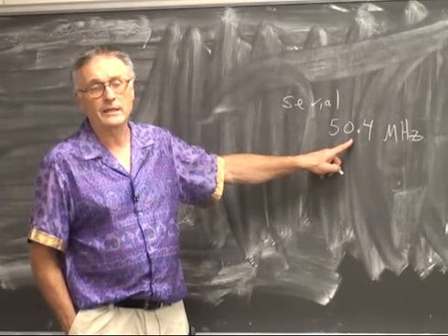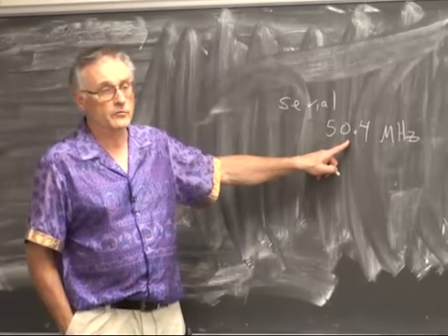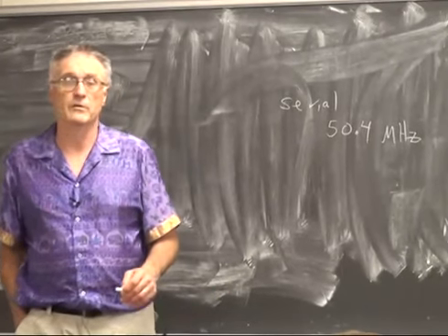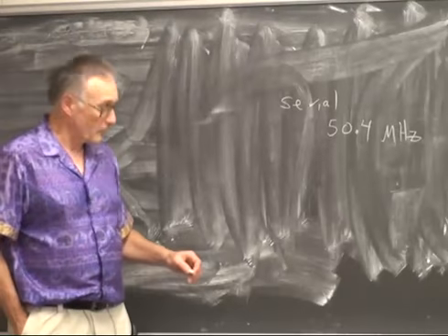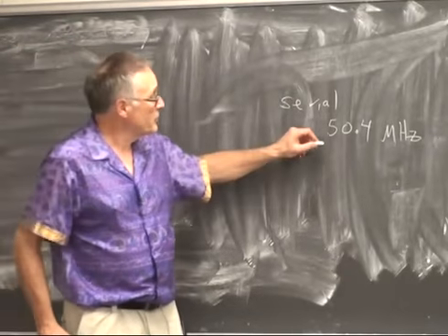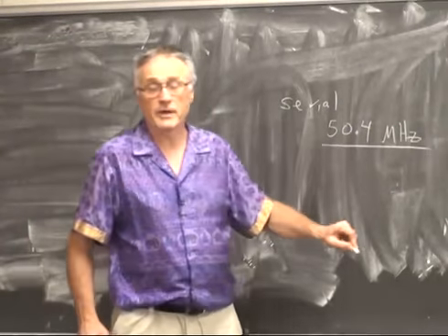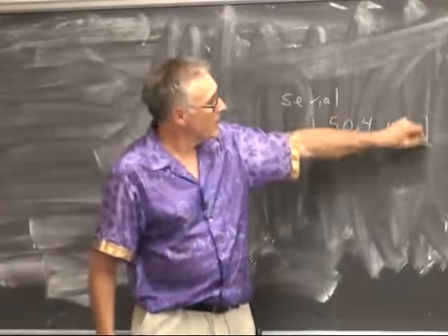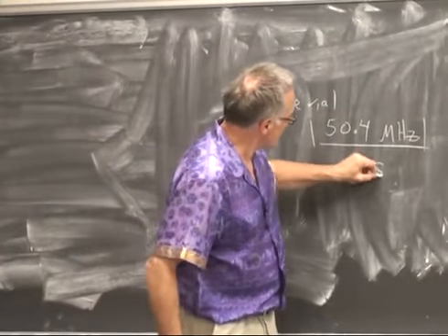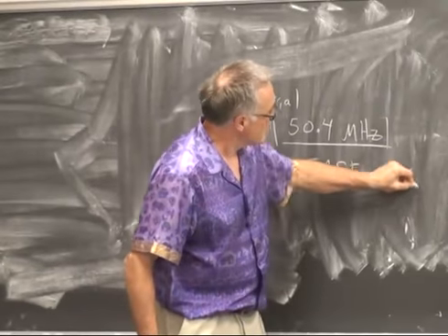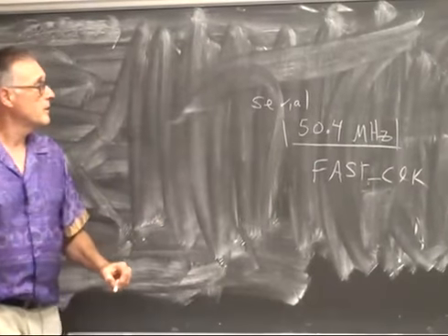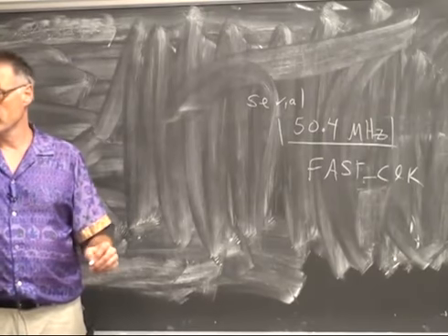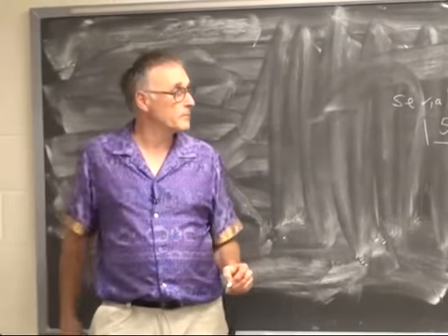What possible reason did I have for using 50.4? Well, it happened to be exactly twice the video control frequency, so it was handy because it was phase locked with the video control frequency. But to get the baud rate right, to see characters on PuTTY, you need to set the so-called fast clock to 50.4 megahertz. And that worked, yes, right? Yesterday it worked fine, yeah.